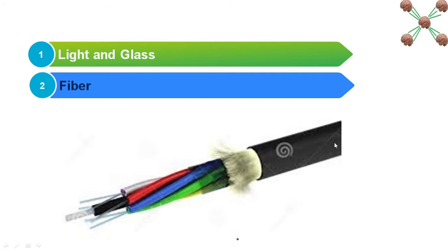If the cable is opened in front of you, you can see tubes inside, and each tube carries 2 optical fiber strands. This thread of glass is the optical fiber coming out of this cable. This cable has 12 fibers: 6 tubes, each with 2 fibers.